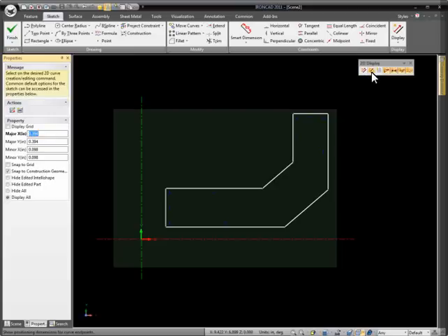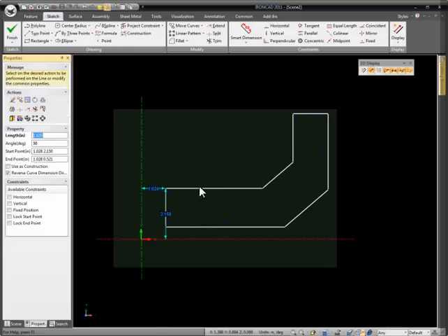Let's start off with the endpoint position information to give you an idea of what this means. Basically, on any element that you select, you can get information on where the curve is with regards to the XY coordinates by default. For example, maybe we want to move this bottom line to be right at the zero placement point on the sketch. We just select the dimension, double click it and type in the value, and our curve will automatically change to that.